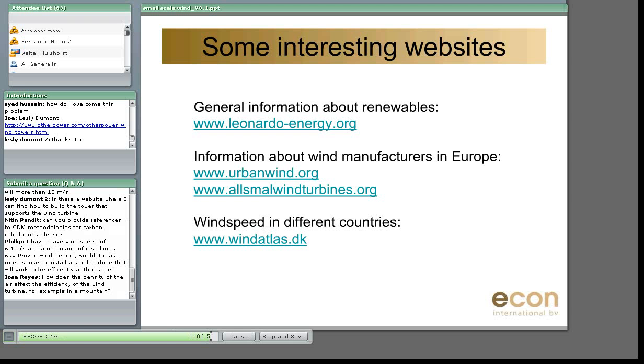Well, density of the air affects directly, obviously, the power available from the wind. You can test this effect with the RETScreen module, where you have the possibility to introduce the atmospheric pressure of your location. Atmospheric pressure influences directly the density of the air, and so does temperature.